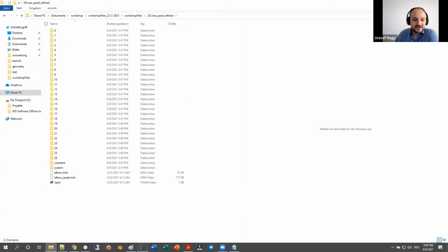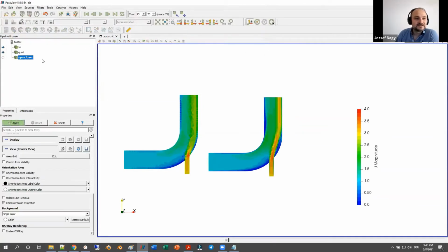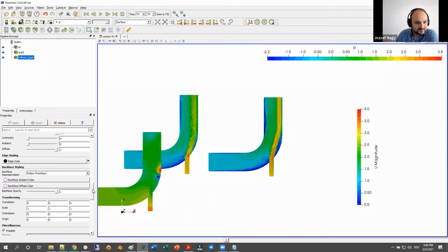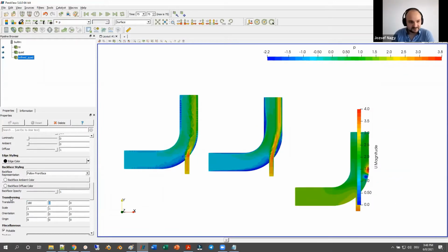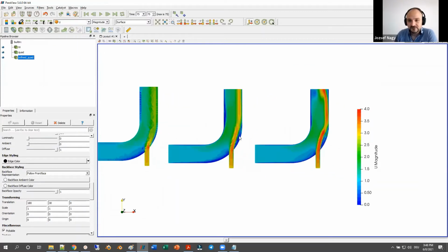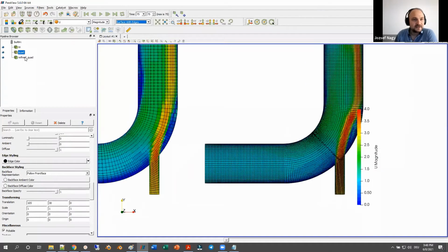Maybe I show you that we can also load in just intermediate results, the quad mesh open.foam file. So this is now the refined quad mesh. So again, it is moved. So I will just move it by, I don't know, 2. No, that's too much. 180, that's okay, and 30. And then let's visualize the velocity. Okay, and now in order to compare these 2 meshes, quad and quad refined, you can see that this is indeed a finer mesh than the one here.